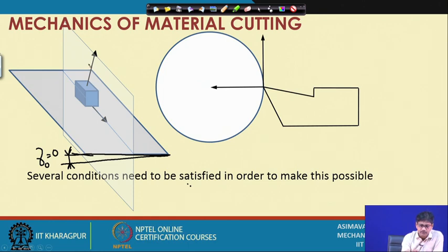In that case, the full forces of this body coming down the inclined plane is only defined by the normal reaction and the frictional force, and therefore, it will be contained in this plane perpendicular to this particular plane. Okay. So, this is the cutting edge, this is our chip, this is the orthogonal plane, orthogonal rake is 0. Sorry, I made a mistake.